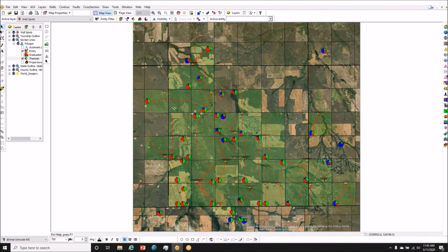Okay, so that's kind of setting up all the map objects there. Setting up how I want to print all that information out, send it out to the PDF file, or send it out to an image file, and try different options with it as well. The image file, the PDF writer, and the plotter images. Sometimes they'll have different options for how those objects are rendered, either depending on the image viewer or the plotter driver that you have available for it. ESRI provides some drivers if you notice that things aren't printing out correctly in that final presentation.